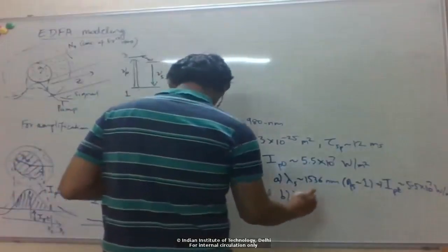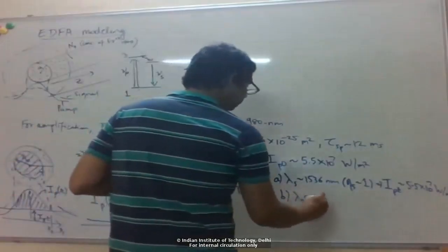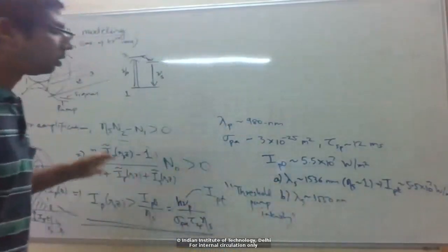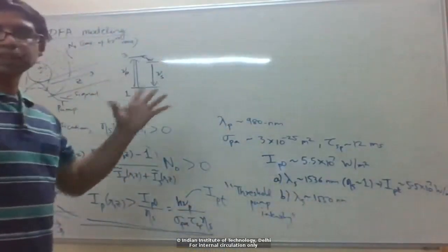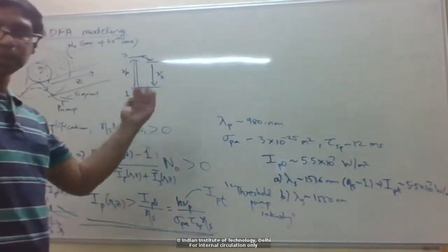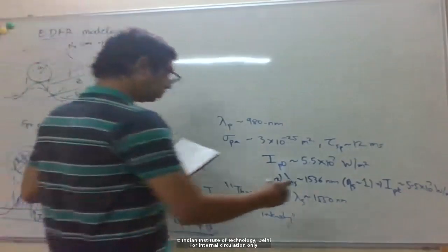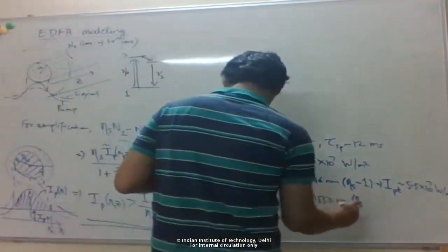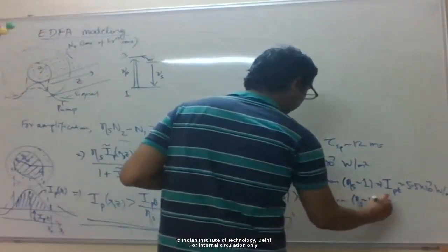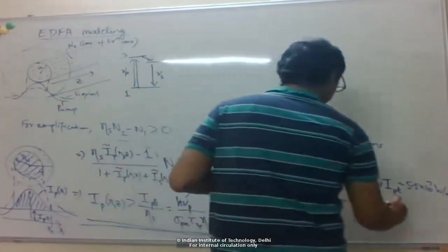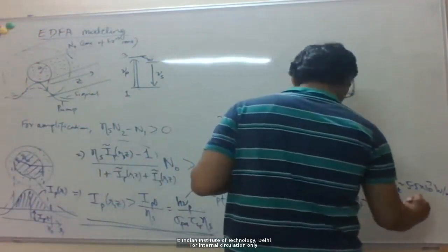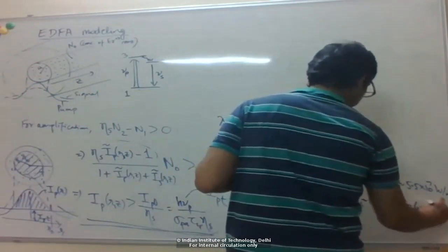So I move to slightly longer wavelength, let's say 1550. Recall last class we discussed how the absorption and emission cross section varied with wavelength. And for longer wavelengths, the emission cross section became higher than the absorption. So this eta is 1.34 for 1550. So the threshold intensity is lower, okay, so 4 times 10 to the 7.